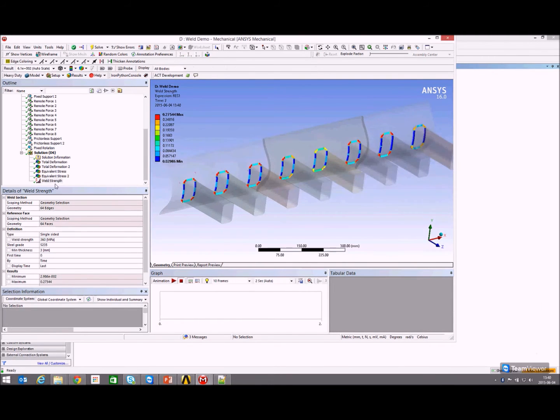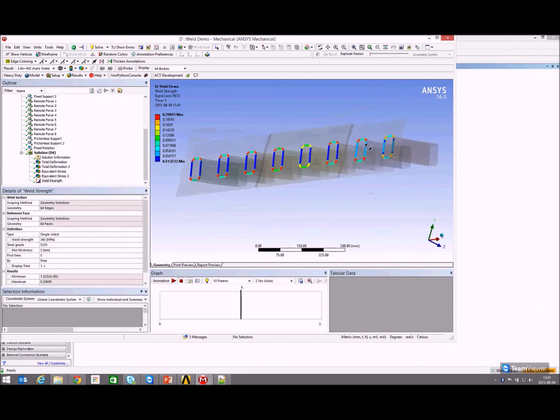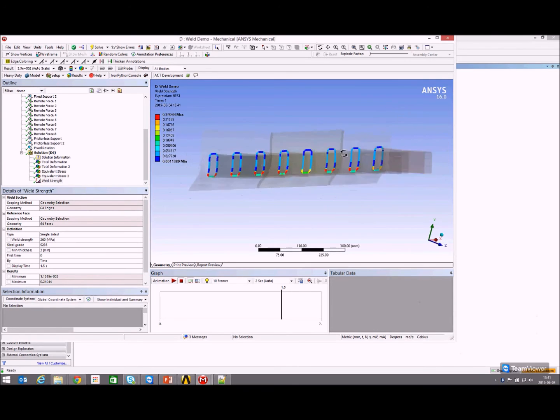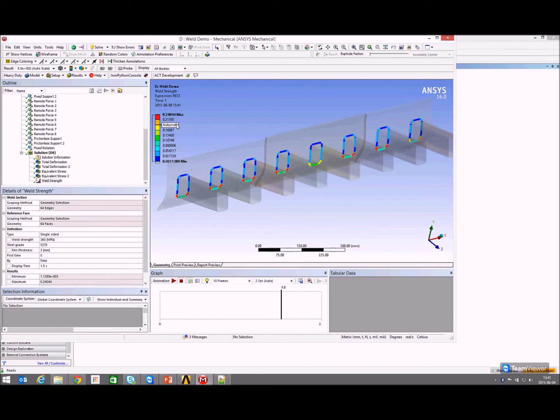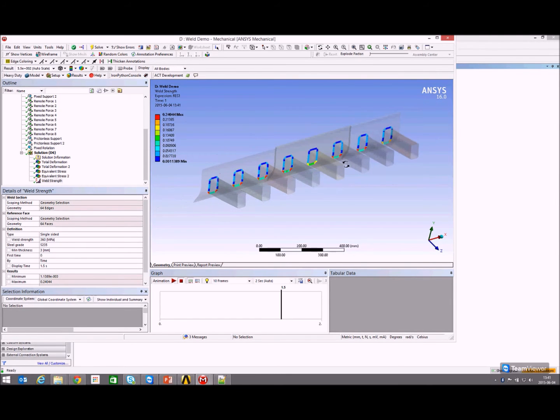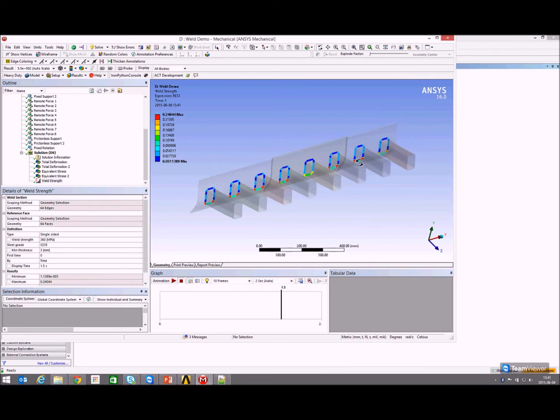And there we go. By default, this was the last load step. Then I can select, if I want, the first load step, so doing the evaluation again. Or if I want, I can even take interpolation, the mix between first and second load step. As we see, there are slight differences in the results, depending on the connectivity and if you have a weld model or not, but very similar results.